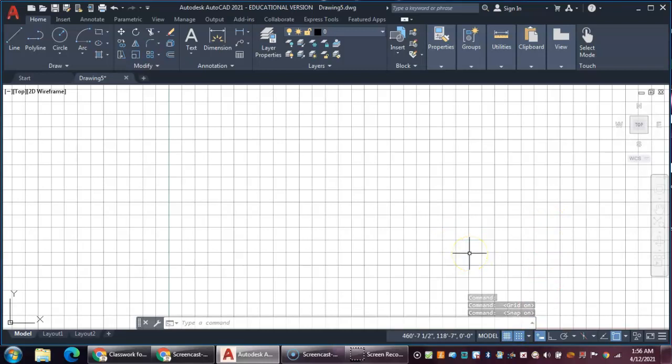Now, to begin the drawing of the baseball diamond, we're just going to use the line command and dynamic input. So we'll go ahead with the line command here. When we're talking about dynamic input, that's where you see the prompt that says specify first point. Here's my dynamic input. Notice that it's on. I'm going to turn it off. Notice now I no longer have that, and it's no longer telling me where those points are. Dynamic input is a very powerful tool, and I think you'll want to be using it most all of the time.